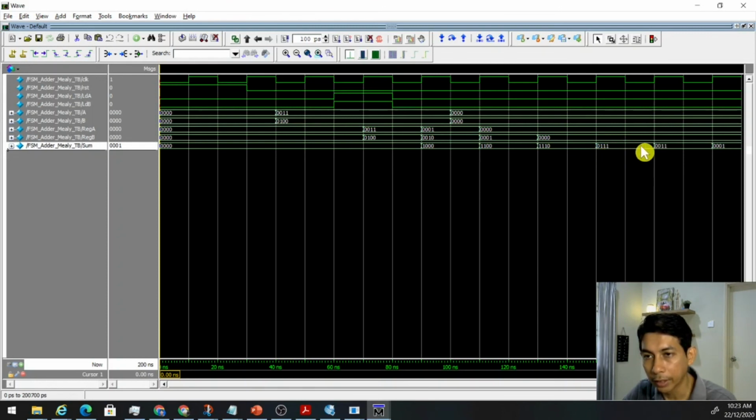This is 7. We can see that 0111 is 7. So this is the output after 4 clock cycles of shifting, 1 2 3 4, we get the result. This indicates that our design is correct, based on the output here.